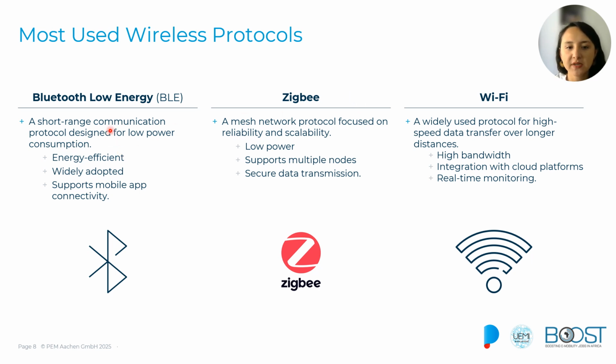One of them is, for instance, Bluetooth Low Energy. This particular protocol is very useful in short range and low power tasks. It is interesting because as we are trying to monitor batteries that have a limited amount of energy, we should try to optimize as much as possible. So communication protocols that do not require high energy consumption are going to be prioritized in this type of products.